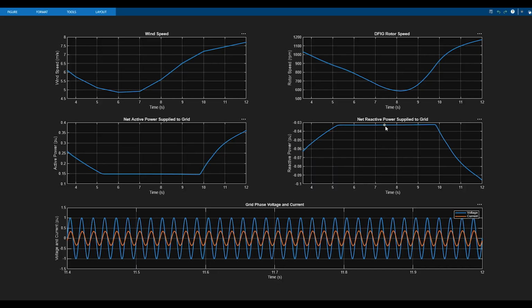The bottom left graph highlights the active power produced, showing a minimum of 0.15 pu and a peak active power of 0.37 pu. The dips are not ideal, especially if you must meet a certain constraint in order to supply enough power to a load. A battery energy storage system, also known as BESS, can be used to mitigate these issues.